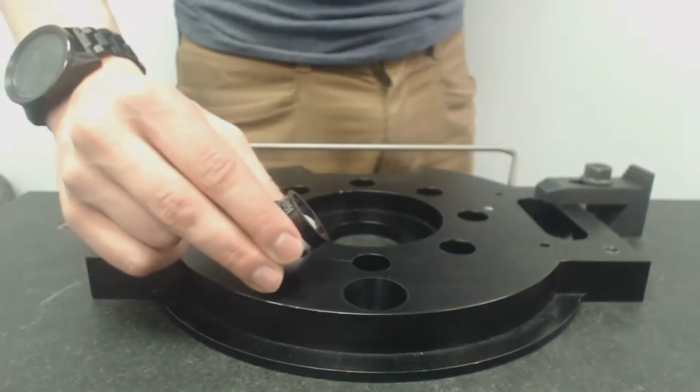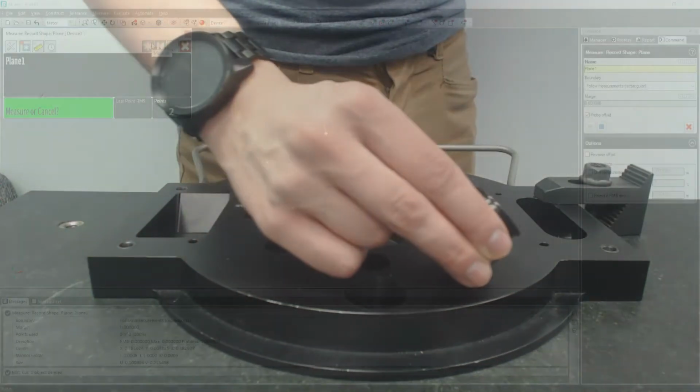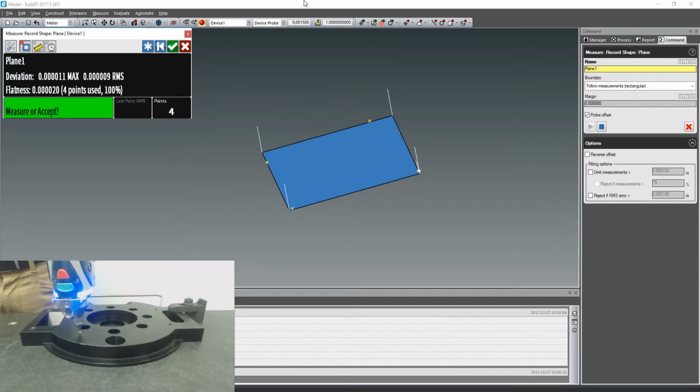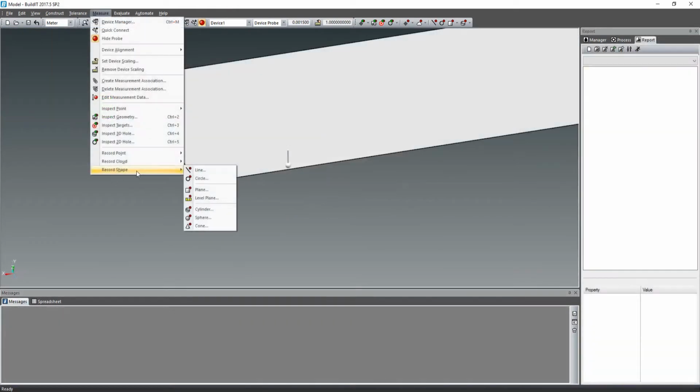The initial orientation of the plane is determined by the orientation of the probe stem if using an arm or the direction of the line of sight if using a tracker. Lifting the probe or the SMR will confirm the orientation before accepting the measurement.